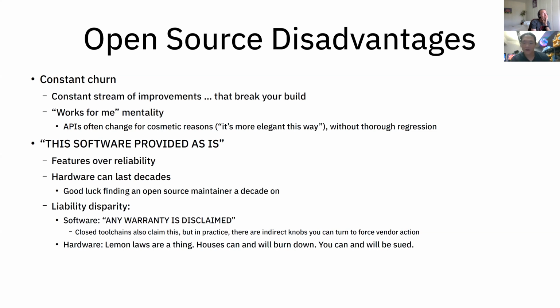But then, you also have the person who has an installed piece of hardware at a customer site, and someone committed a patch that creates a very subtle corner case inside a Wishbone bus transaction, like in the case of two concurrent burst beats and one terminating, the other one crashes and hangs the bus, and you basically don't get caught until you hit a certain corner case in the bricked device, right? That sort of regression is really hard to catch, and those things creep in all the time.